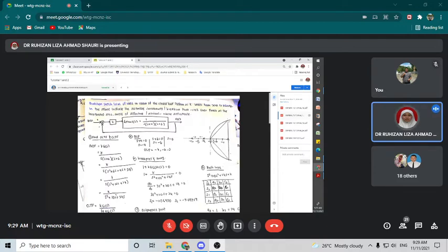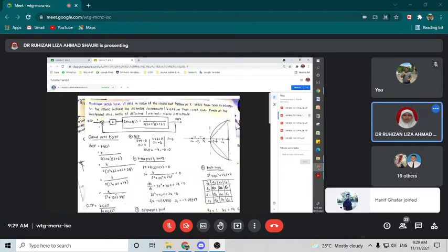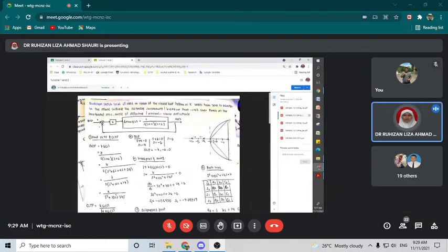All right, so that's why you understand the 8 rules already. But remember, the 5 basic rules give you first information about how the root locus looks like. Do that first. Just briefly sketch your root locus, and then you decide about the additional 3.